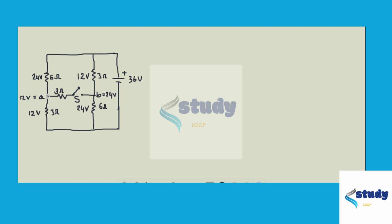So what reaches here is 12 volts. Now to find VAB, this is voltage of A minus voltage of B. VA is 12 and VB is 24, so this gives me minus 12 volts. We are done when the switch is open.